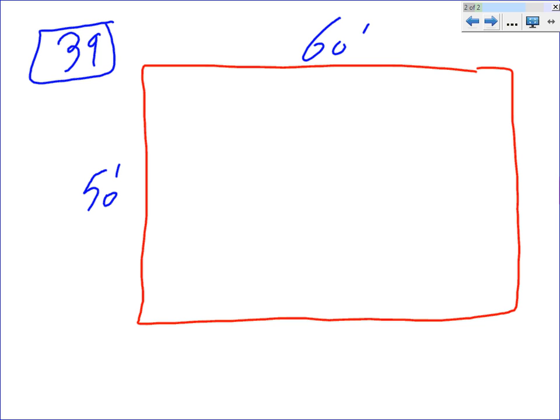I'm going to make them 40 fixtures, and I'm going to tell you why. That's the calculation. Then I take the 40 fixtures and ask myself, what are the 2 largest numbers that I can multiply with each other to get 40? I can get 40 by 4 times 10, or 20 times 2, meaning 2 rows and 20 columns. You want these 2 numbers to be as close to each other as possible. So I have 10 by 4. What else can give me 40?